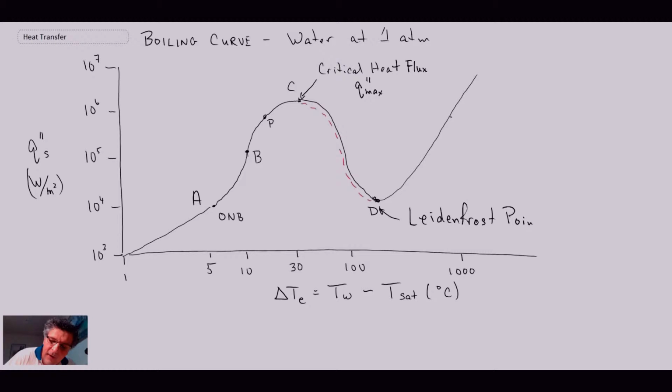And the Leidenfrost condition, if you've ever taken a droplet of water and put it on a really hot stove, you see that it kind of bounces around and skips around. It's because a vapor develops underneath the droplet, and consequently it is free to move around. And that is the Leidenfrost point there, where you have a vapor between the solid and the liquid.